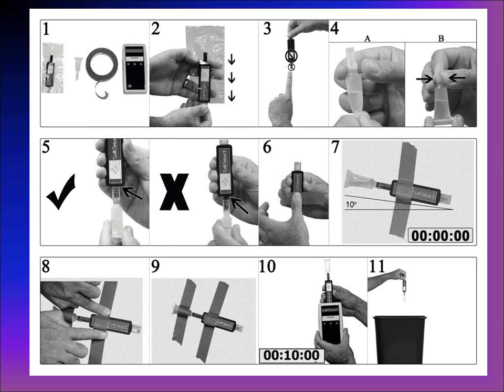After approximately 8 to 10 minutes, remove the test strip from the surface and connect the test strip directly to the conductivity meter, as shown in Figure 10, and read the conductivity value from the display. The meter will store the value and will date and time stamp each value. Up to 255 values can be stored, then uploaded to a computer using a USB connection. Dispose of the test strip and water ampule once the test is complete. These are not reusable.